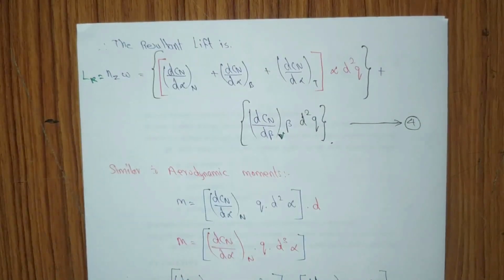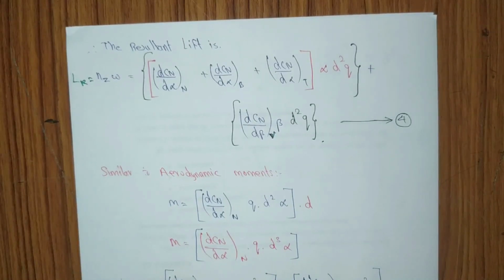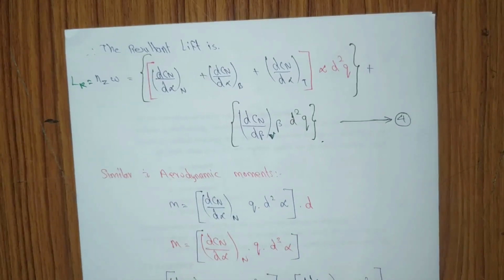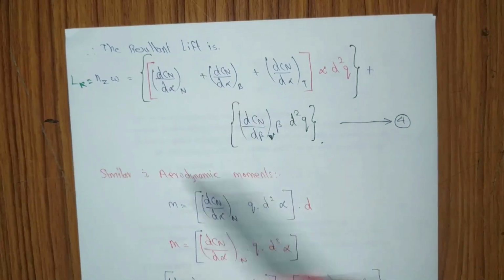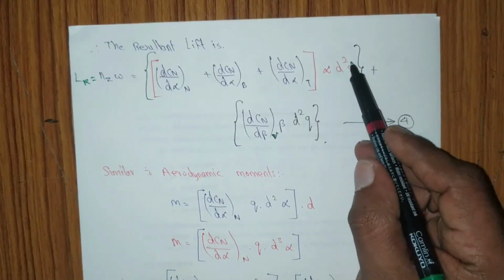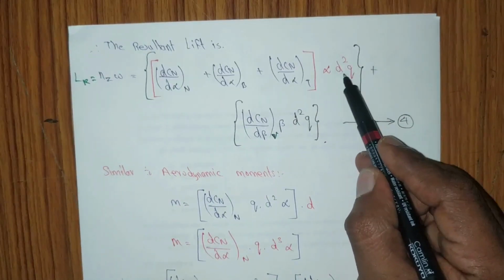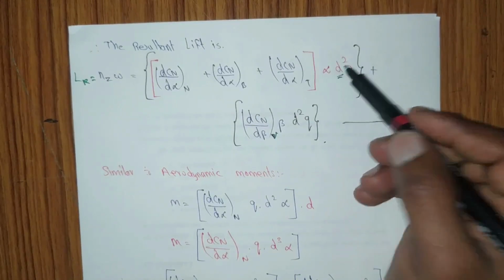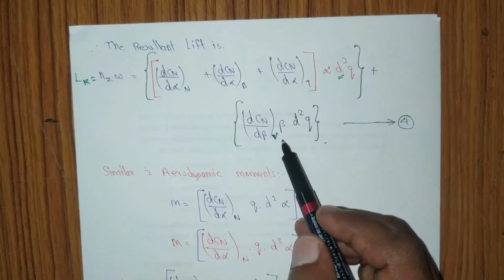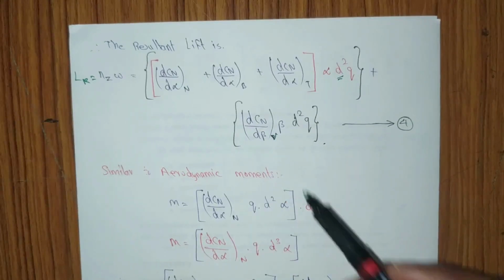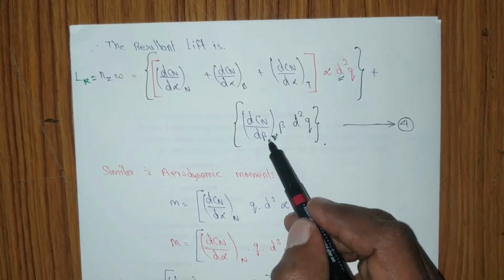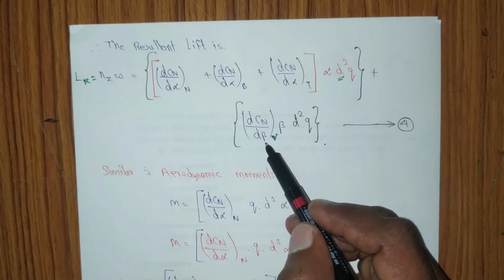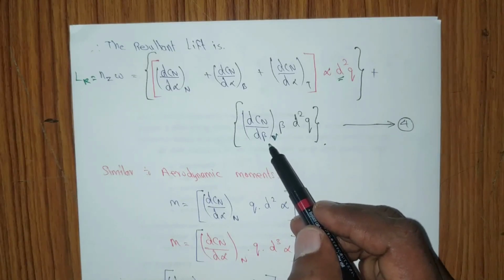The resultant lift acting on a missile depends entirely on how much lift coefficient is produced by the nose lift, body lift and tail lift, with respect to how much dynamic pressure is acting, especially the d square, what diameter the missile has and what angle of attack it is flying. In addition, we also have to consider how much control surface of the fins or the missile body you are fixing, and at which angle it is acting to the surface or the reference axis.